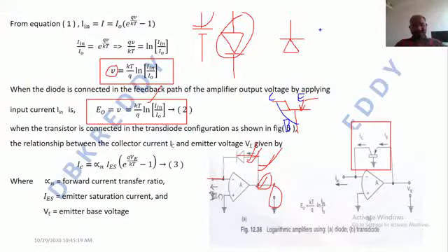So here this diode, I think all of you are aware of this one, right? This diode is whatever the diode we are having. So when you are shorting these two, if I'm assuming this is a base and this is a collector, this is an emitter, then obviously this entire thing will be replaced with one terminal. So now the BJT is converted into the diode format. That is the PN diode format.